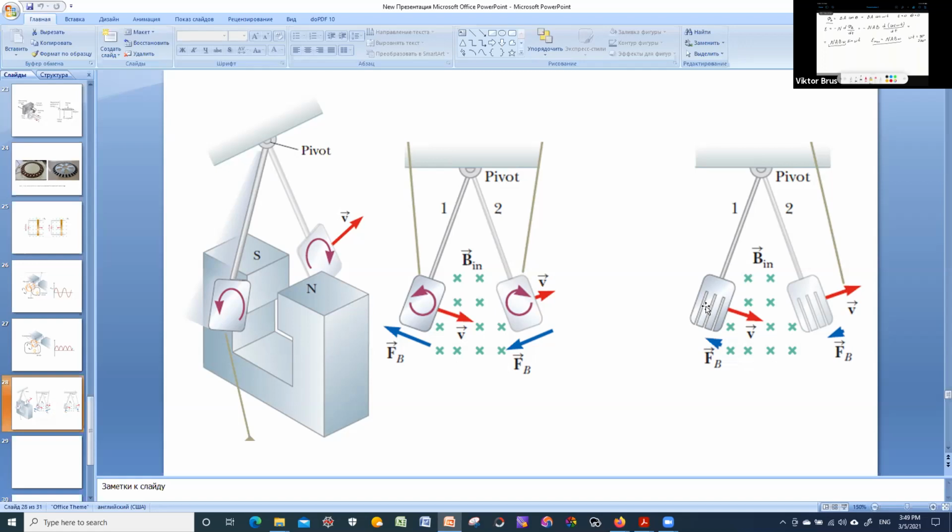So that is made in order to prevent forming large radius eddy currents, like the circulating currents, and prevents excessive loss of energy by heating this ferromagnetic conductive core of the transformer.